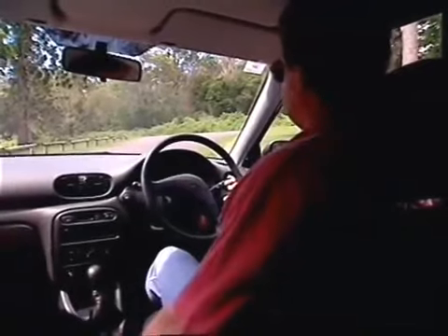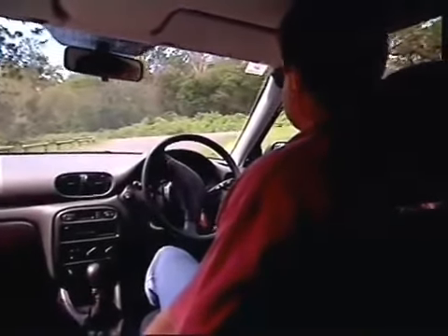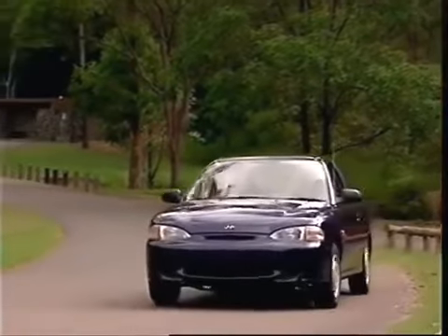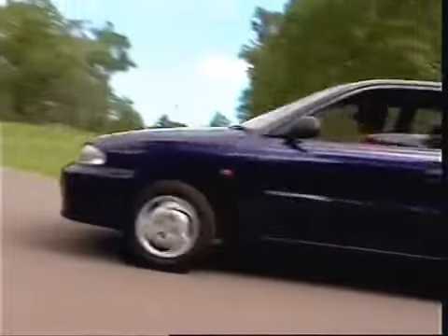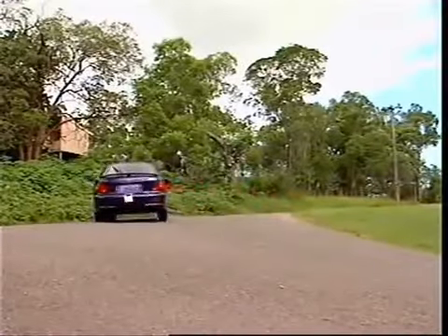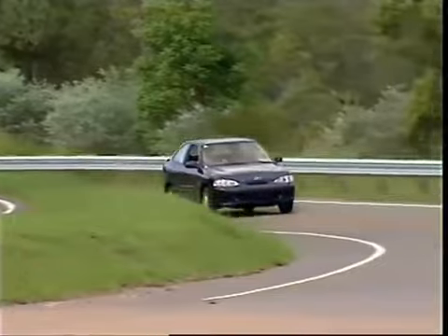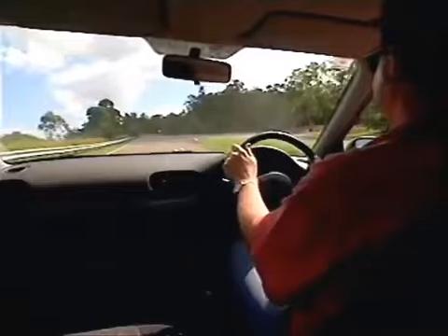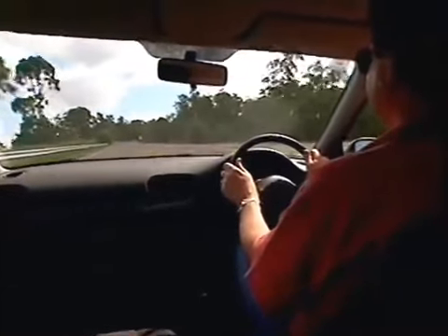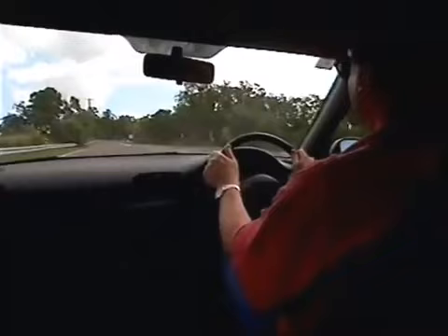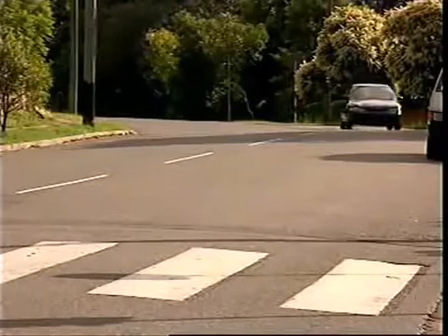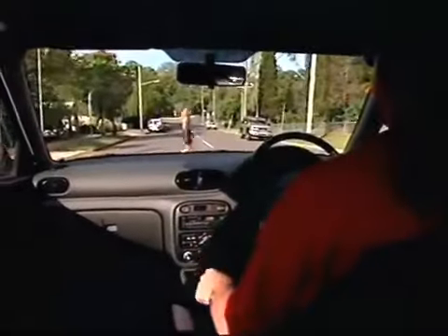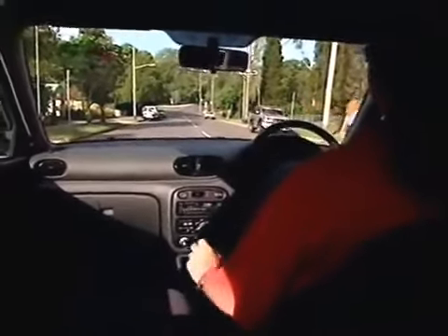When moving the vehicle from rest, slowly releasing the pedal gives a gradual engagement of the drive as the friction facings slip and allow torque to be applied progressively until both units are rigidly connected. When selecting an alternative ratio, that is, changing gears when the vehicle is in motion, the transmission of engine torque must again be interrupted for this to occur. And when bringing the vehicle to a halt, the transmission must be disengaged to leave the engine running at its idling speed.